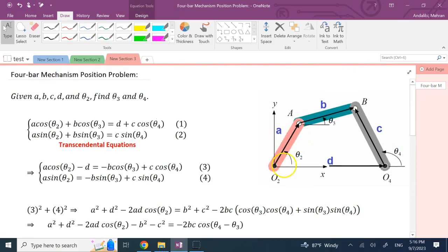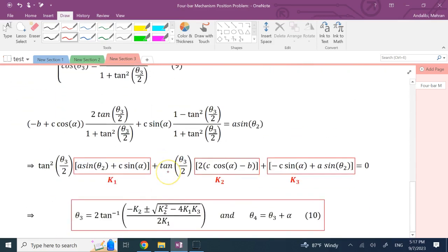And you know, always for one given angle, there are two versions. One is the solution that is going like this, and the other one is basically something like this. If I can draw it properly, hopefully. So it is something like this. You see? So it's not going to be the members like this. This is the second configuration. So this gray member is going to be like that. The green member is going to be like this, and the red member stays. So there are two solutions in general, and you clearly can see the solutions here.